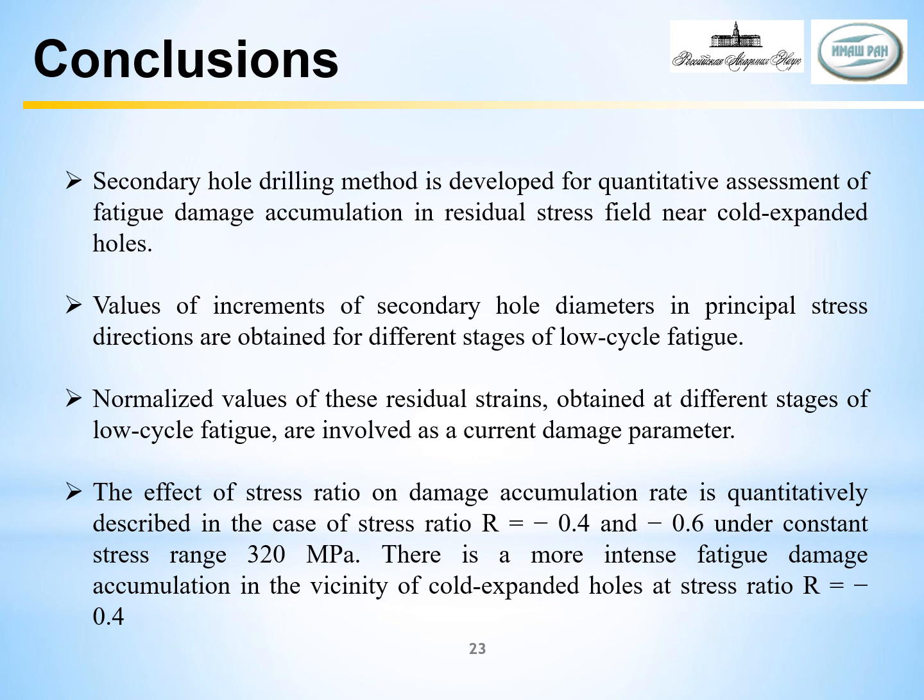The effect of stress ratio on damage accumulation rate is quantitatively described in the case of stress ratio minus 0.4 and minus 0.6 under constant stress range 320 megapascal. There is a more intensive fatigue damage accumulation in the vicinity of cold expanded holes at stress ratio minus 0.4.